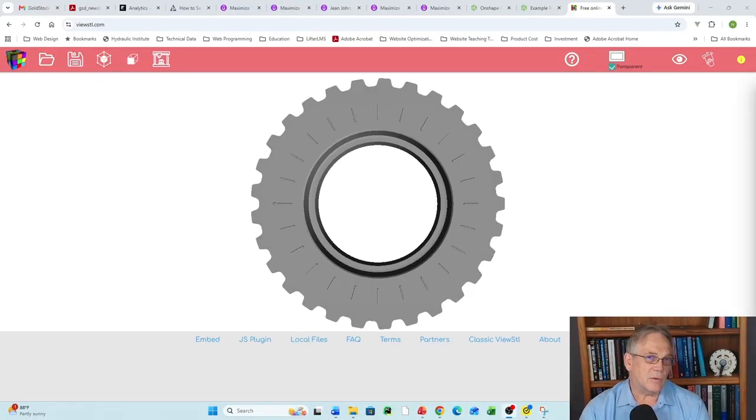For the second method, we're going to look at additive manufacturing. This method is particular to when 3D printing utilizes a layer type philosophy and then hardens the individual pieces that stay behind and form the actual part that you're going to have. For this particular example, I'm utilizing a 145:1 gearbox that was printed with a 3D printer and then assembled with some metal components. As it turns out, this particular gearbox is the one on my bookshelf over here, and the gear that you see on your screen is the internal main wobble gear that wobbles from side to side to give you that 145:1 reduction.